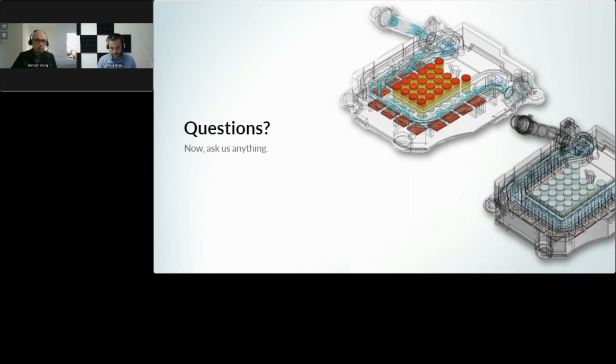Yes. All right. Somebody wants you to review the importing options for proprietary material information, including stress-strain curves. I wonder if it's something you can talk through about how to do this. Yeah, I don't want to start a screen share again, but in the material dialog where you would add a material, you have the possibility to define the material model you want to use, and then upload, depending on if that material model supports or needs a stress-strain curve, you would upload it as a CSV file.